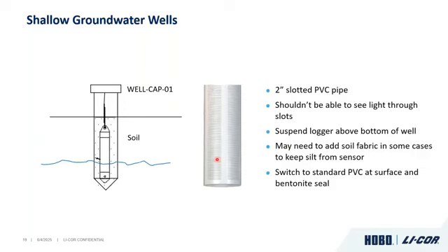Also, a note about shallow groundwater wells: I do see a lot of perforated pipe or slotted pipe, even with some fabric around it too. There's well sock that you can put around that pipe just to keep even more silt out of it.